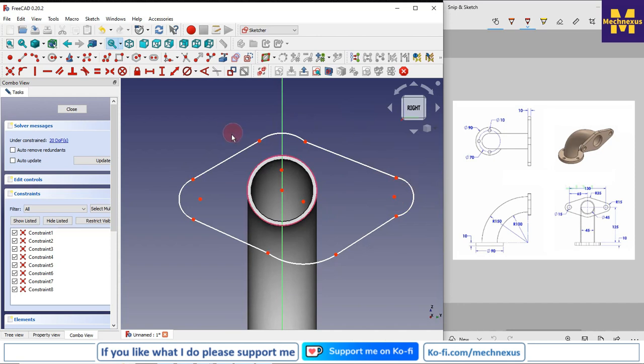So first we will give the tangential constraints to all our arcs. So select this one and this one, give tangent, same way for this, and repeat the same process for the other arcs.